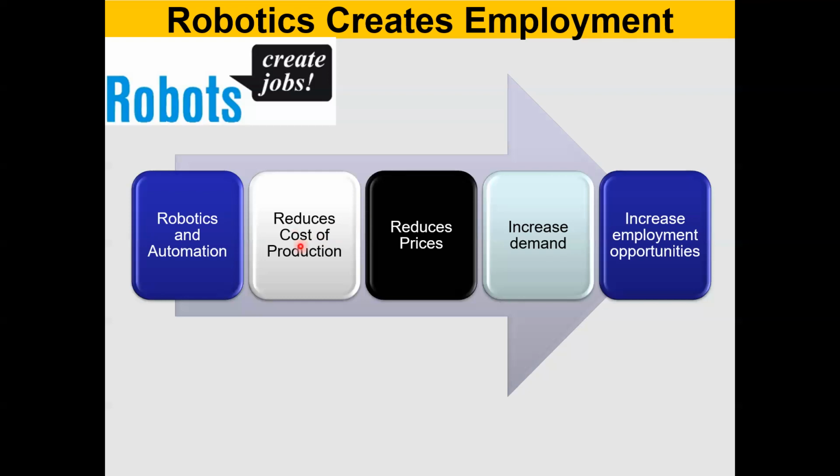Okay, so if you use robots now, you can purchase them at a relatively lower cost than a decade ago. Now the robots have become affordable to many industries. Not only are they affordable, they are also easily programmable. You don't need an engineer to program a robot now. A technical person can be trained for the job. How to install, how to calibrate, how to program a robot, right? Installation, calibration, programming. These are the three things you need to do if you purchase a manipulator. A technical person can do that. You don't need an engineer.